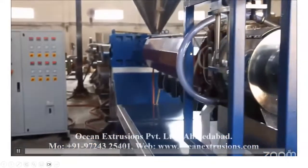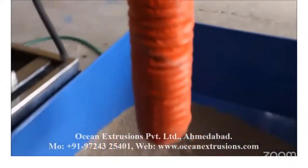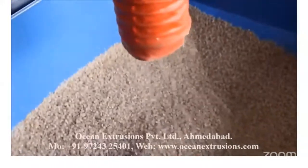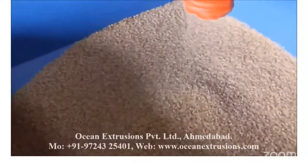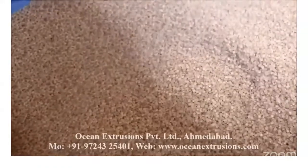This is a very simple process nowadays because in the old days, we had a long cooling trap, and we required a lot of space for that. But now, this is a very immediate process, and the production is also very fast. The materials which are not hydrophilic in nature can be used on this machine. That is a wet die face cutter. Remember this. And I told you the dry die face cutter is used for non-hygroscopic material.